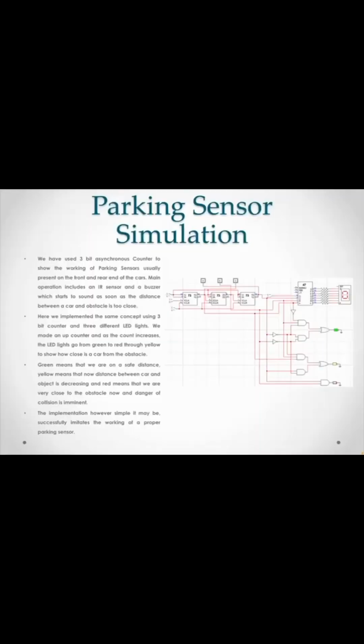Hi, my name is Taif, and now I will talk about the parking sensor simulation. We have used a 3-bit asynchronous counter to show the working of the parking sensor usually present on the front and rear end of the car. Its main operation lies in IR sensors and buzzers, which start to sound as soon as the distance between a car and obstacles is too close. Here we implement the same concept using a 3-bit counter and 3 different LED lights.